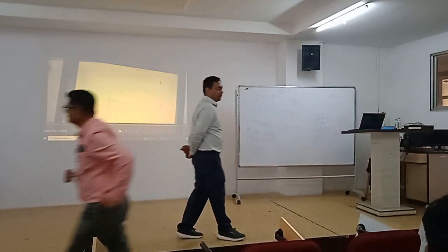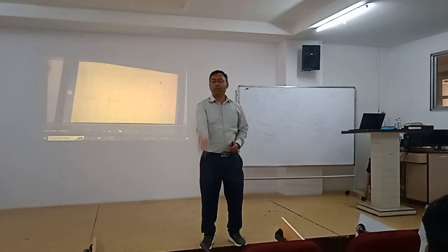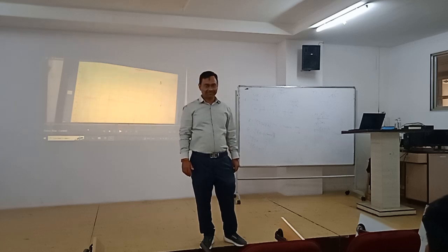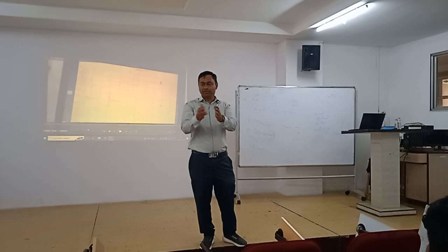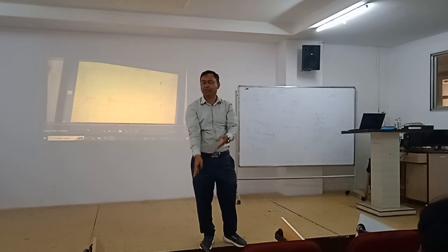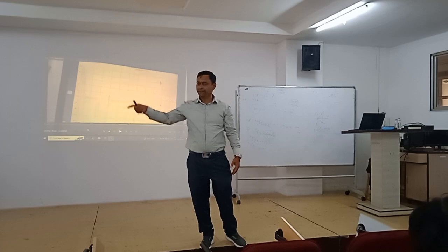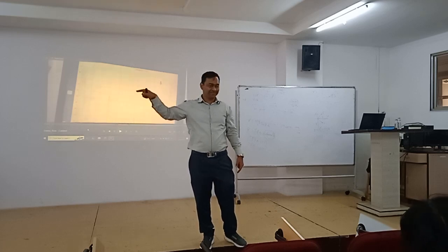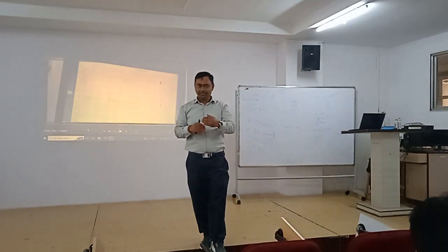See now what happened? Already your motor is moving at a very high speed, so as soon as you open the valve, suddenly flow will increase to a very high value. Now the controller is in action. Flow is high, desired flow is low, so it will decrease the motor speed again. I hope this is clear, right?